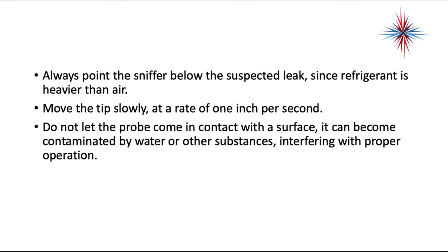Always point the sniffer below the suspected leak. Refrigerant is heavier than air. Move the tip slowly, at the rate of 1 inch per second. Do not let the probe come in contact with the surface. It can become contaminated by water or other substances, interfering with proper operation. These are very sensitive tools, okay? They can become contaminated. A lot of times they have filter material in them, and sometimes the sensors are changeable. So read the manual that comes with it and find out how you're supposed to service it.